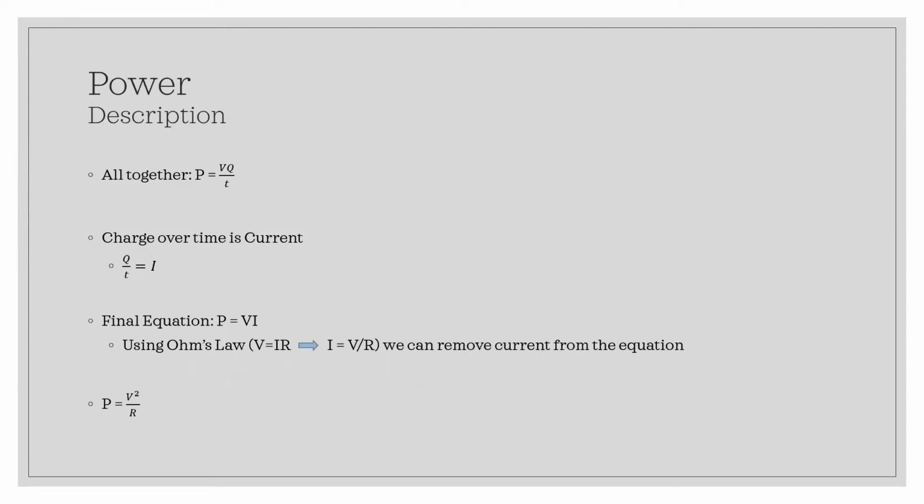So if you only care about the power as it relates to voltage, you can use Ohm's law, V equals IR, substitute I equal to V over R for I, and you get V squared over R, and now you have power where current is not directly calculated. And you can do the other way too, where you wind up with I squared times R, because V times I, substitute I times R again, I squared times R.